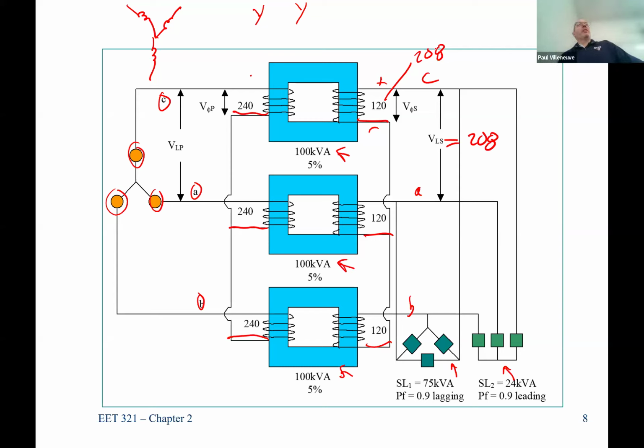How about some less obvious ones? We know your house is single phase, right? How about a Walmart? That's single phase or three phase? Most likely going to be three phase. And the only reason why it's most likely three phase is because it's a big load. I mean, you got 100,000 square feet with refrigeration and air conditioning and all that stuff. It just is a really big load. And the utility is going to be sorry, we can't give you 5 MVA on a single phase line. It would just destroy our system. So Walmart almost guaranteed will be three phase.